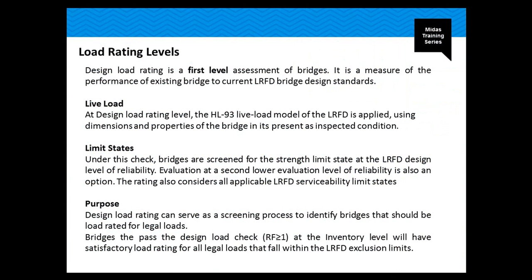The design load rating is the first level assessment of bridges. It is the measure of the performance of the existing bridge to the current LRFD bridge design standards. Plain simple: the live load at the design level, the HL93 load, is used, using dimensions and properties of the bridge in its present inspection condition.